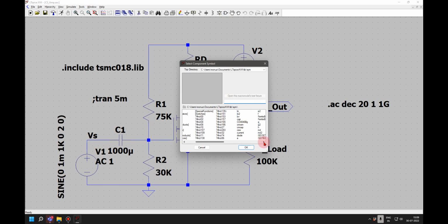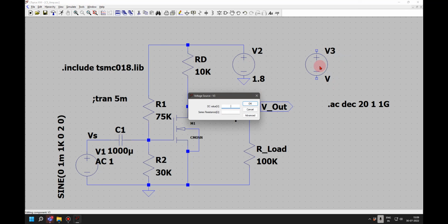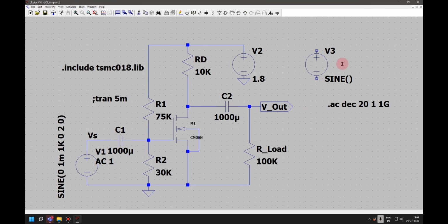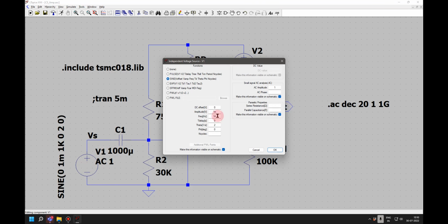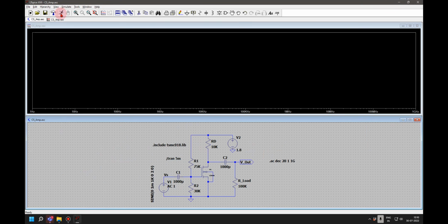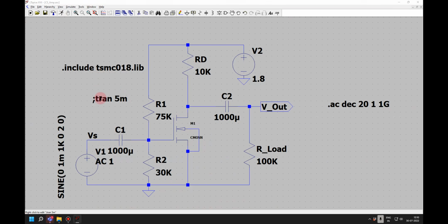Now once I go to source voltage here, you can go through my videos, you will get it. You right click here, advanced sinusoidal signal. So a DC offset, amplitude and all these parameters will come. I have taken a 1 millivolt, 1 kilohertz signal here. I have put these resistances that we discussed in the class, and I am doing a transient simulation.